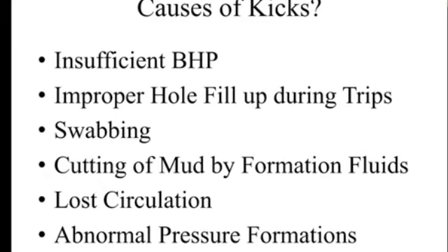During tripping out, we are basically removing the drilling string out of the wellbore, and the level of the drilling mud drops because we are removing the volume of the drilling string. We have to replace the volume of the drilling string by drilling mud in order to maintain the bottom pressure, or static pressure in this case. If we fail to do that, then bottom pressure drops and it may go below the formation pressure and kick happens.